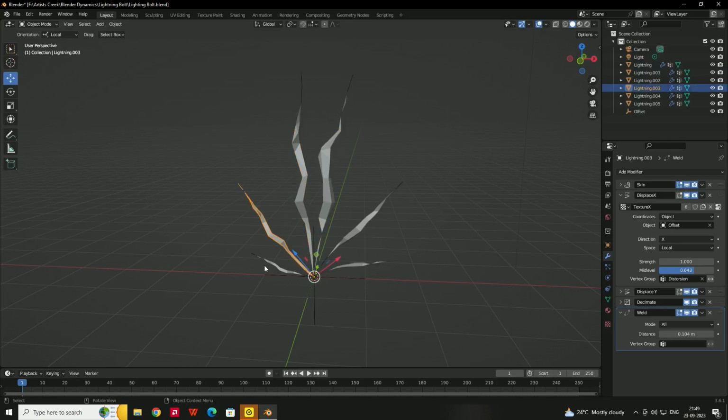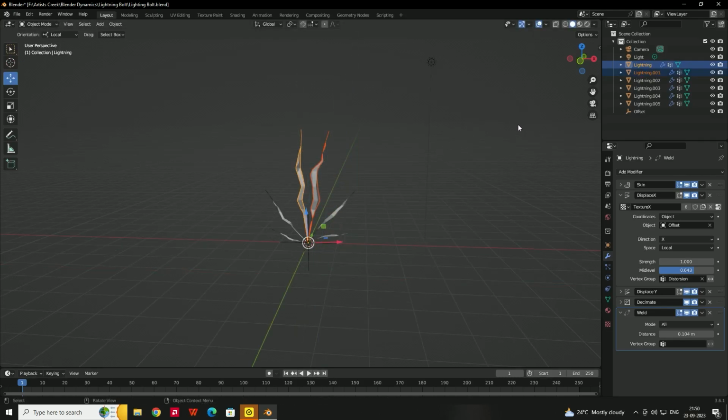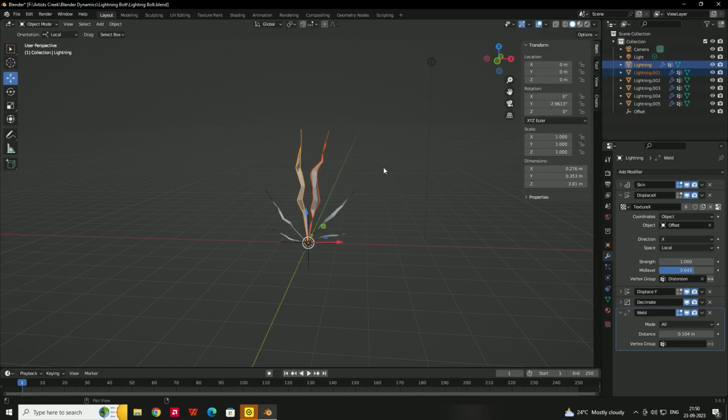So everything is in the local direction here. Now we will animate this first. In order to animate, I will open the translate controls by pressing N. I will select this object and we can give the animation for the location.